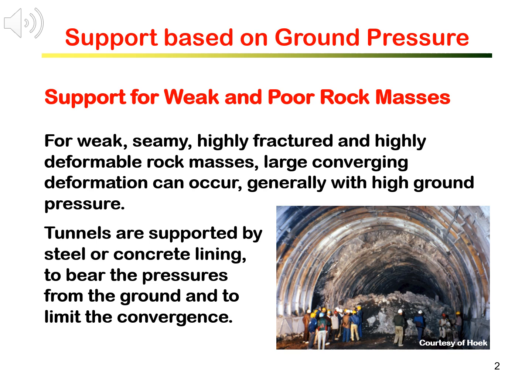For weak, semi, highly fractured, and highly deformable rock masses, large converging deformation can occur after excavation, generally associated with high ground pressure. You can sense how much deformation occurred in this tunnel here. The background tunnel has suffered the squeezing, and the foreground is the re-excavated tunnel with the desired size.